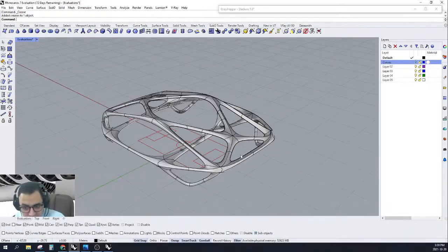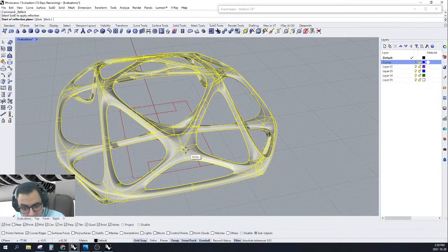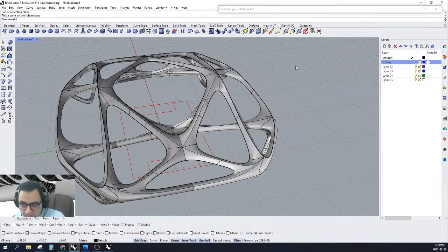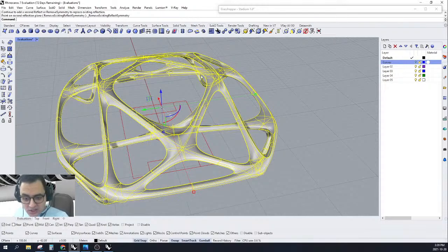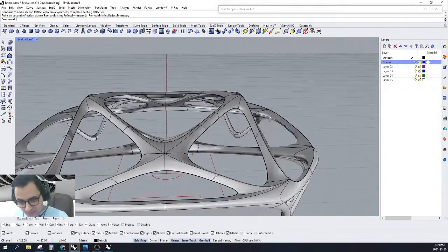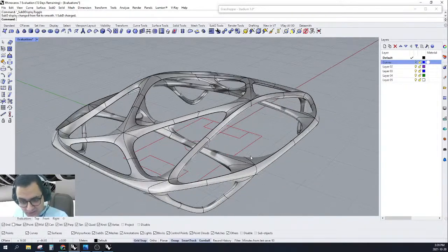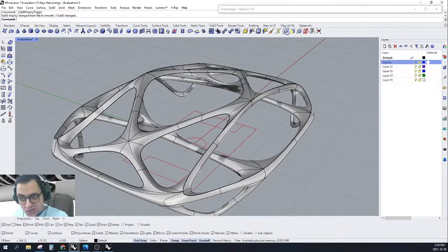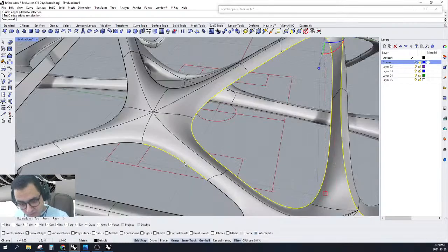Yeah, I can do the same, or I can simply reflect from the middle to the middle and keep this side, and simply right click again and remove whatever we did. Okay, so after that, this is great looking. After that, select all the creases that you created, all of them.